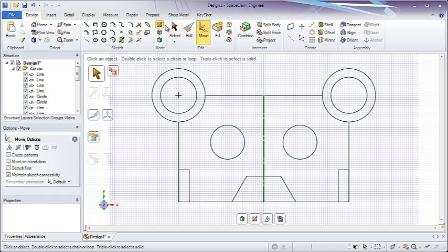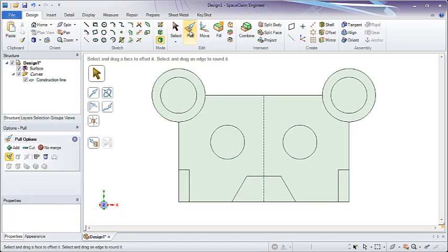And when we're going from sketch to 3D, all of the lines and curves will form surfaces provided they form closed boundaries. For instance, this was a closed boundary versus a line sticking off into space. And you'll also notice the duplicate edges and the lines we've created are not important. These will create just one single edge in 3D, which again, I can go to by either clicking the 3D mode button or Pull. Thank you for watching our sketch section.